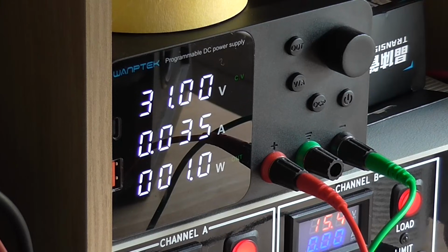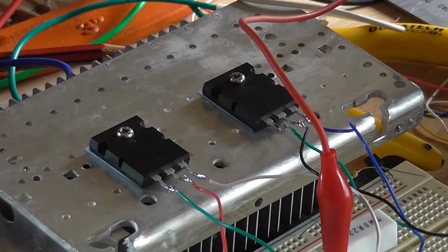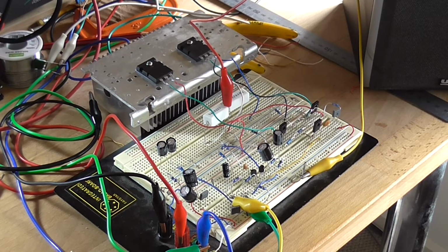Tina says 43 mA quiescent current. My power supply, albeit it's probably about 2 milliamps out, says 35, but different output transistors as to what is simulated, and Tina doesn't actually have them by default. You'd have to download third-party models and stuff. I can't bother messing around with that stuff. But overall, we've proved that the simulated design actually works in the real world.